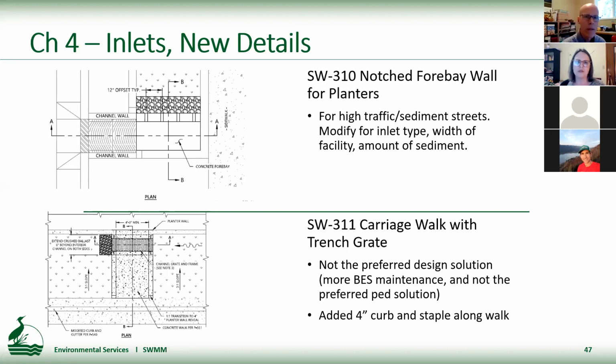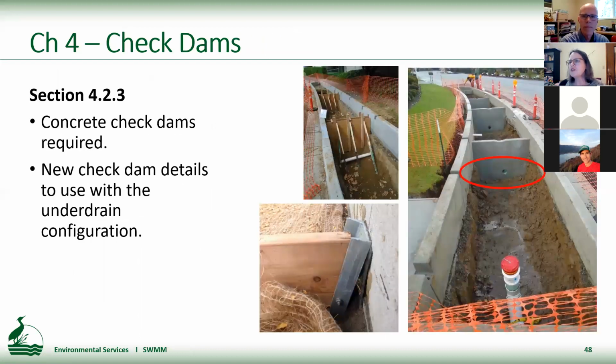So this connects to bays of the facility with the carriage walk. This isn't the preferred solution, but it can be an option in some cases. And then check dams, the changes that we're not allowing the wood check dams any longer. We had problems with maintenance as well as construction. So concrete check dams are what is left.